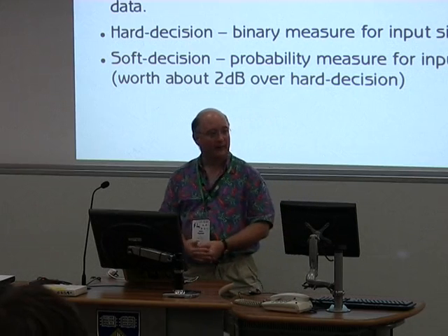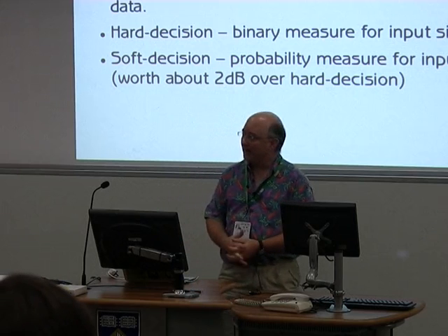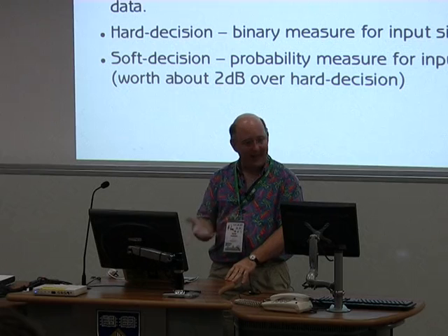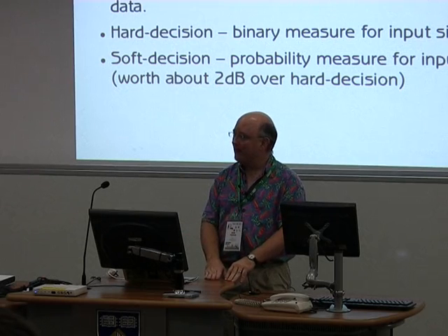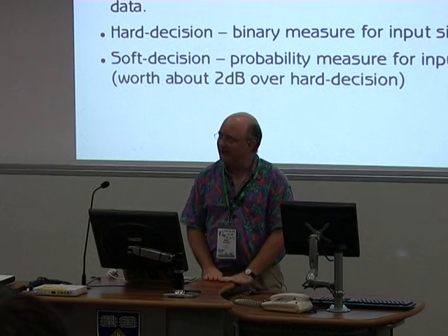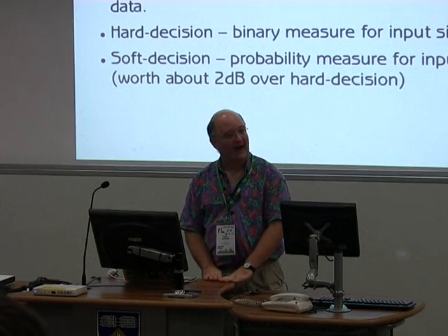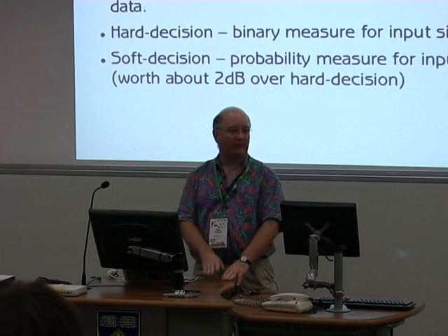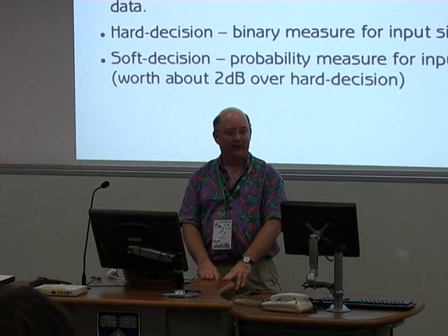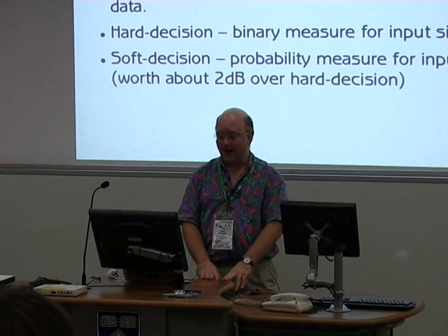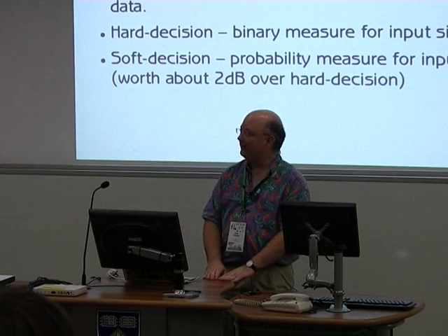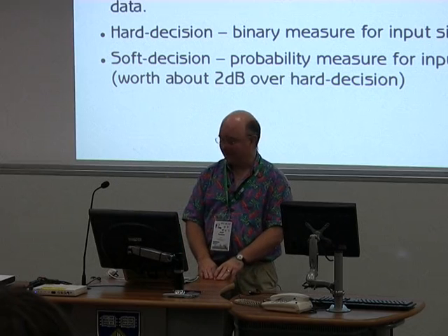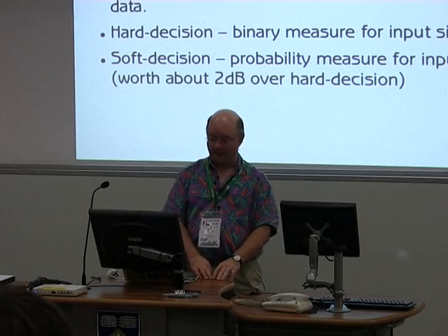When I discovered that our hardware did not have nice support for getting soft decision data out of it, I wrote a little note off to the manufacturer and said, this part is awesome, fabulous transmitter, awesome receiver, but I don't get any soft decision data except 1 bit at a time per interrupt. And the manufacturer said, yeah, you should just use the hard data. It's way easier to get. And it's like throwing 2 dB on the floor? I don't think so. How many interrupts can my processor take per second? And it turns out that the STM32L is quite happy to take 1 interrupt per bit.